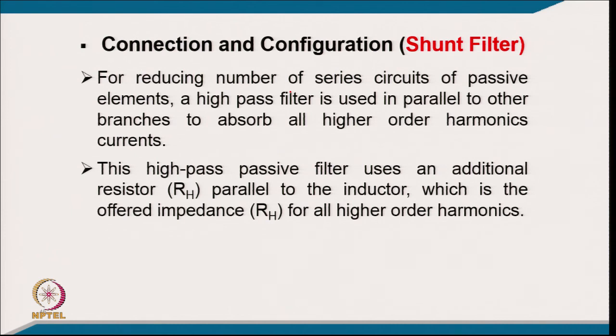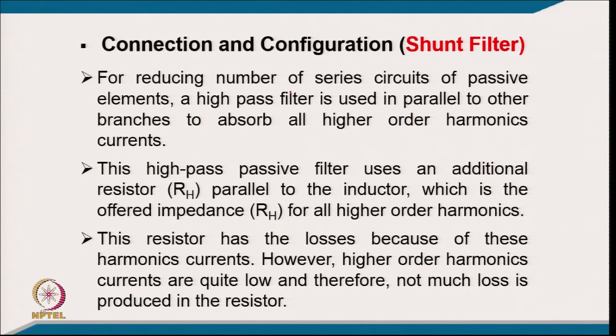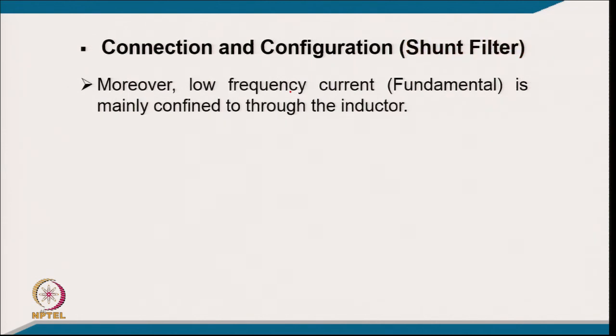Of course, there will be losses corresponding to that, but the energy or power associated with all higher order harmonics is quite low. The resistance has losses because of these harmonic currents; however, the higher order harmonic currents are quite low and therefore not much loss is produced in the resistor. Moreover, the low frequency current, that is the fundamental, is mainly confined to the inductor, which has reasonable inductance. So, you will not have a very large current flowing into the inductive circuit either.